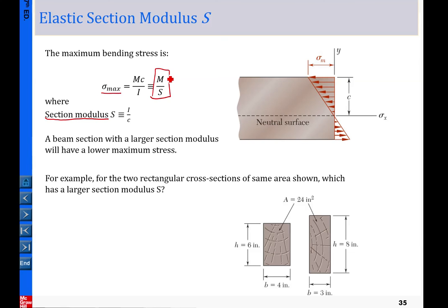So we are given the magnitude of the bending, and given any material, we can look up the data book for the section modulus corresponding to the type of beam we select. So from here, this is a given loading, and this is given from the material data book. Then right away we can predict the maximum stress.